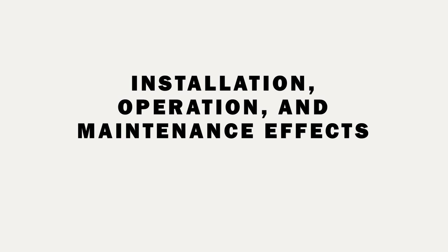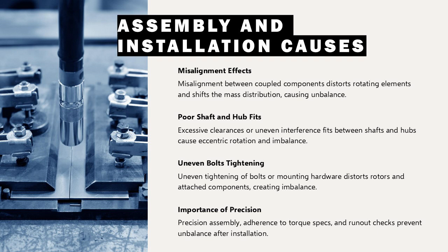Assembly and installation causes, operational and maintenance-induced unbalance. Improper assembly and installation practices are frequent contributors to machine unbalance. Misalignment between coupled components can distort rotating elements, effectively shifting the mass distribution.